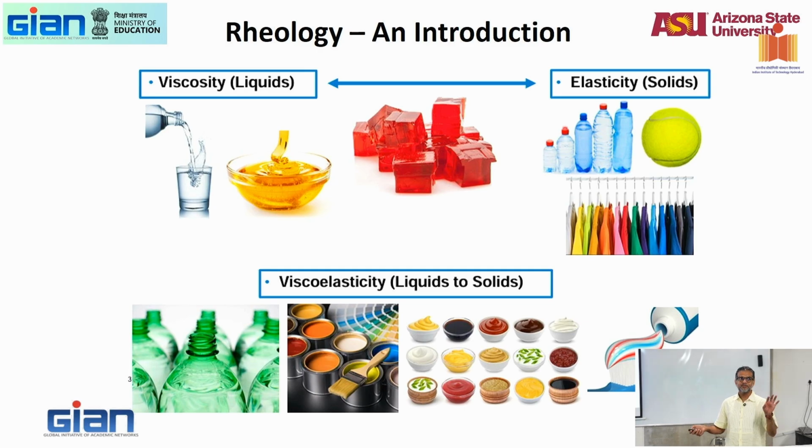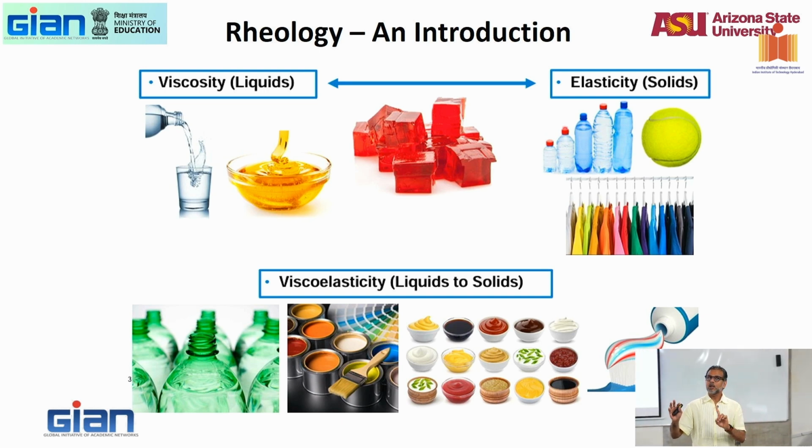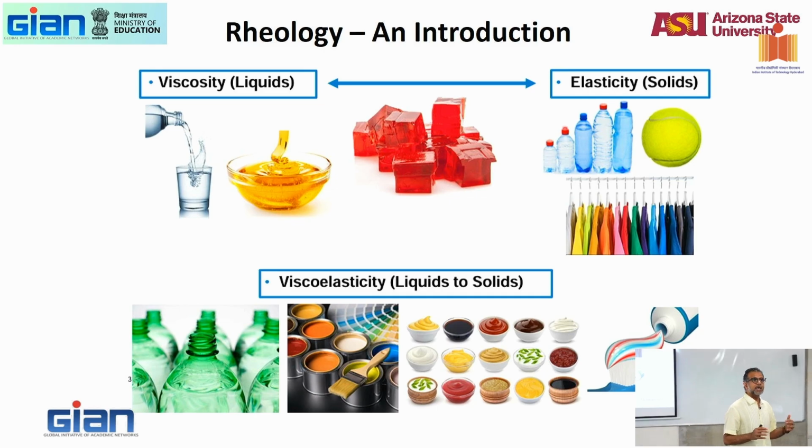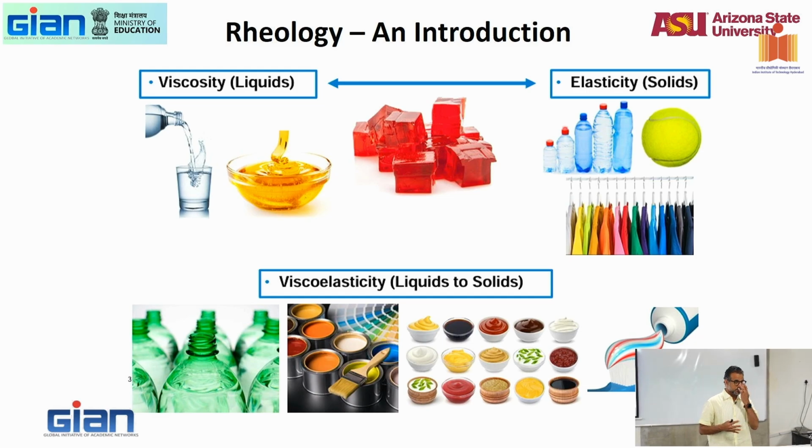All right, so viscosity is to liquids as elasticity is to solids. Viscosity is that fundamental property of liquids which is similar to the elasticity of solids. For a linear elastic material, elasticity is a proportionality constant between stress and strain. Similarly, viscosity for a liquid is a proportionality constant between stress and not strain, because liquids are time dependent, so we use strain rate, right? Strain as a function of time, the rate of change of strain with respect to time.